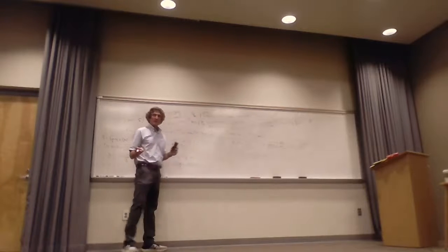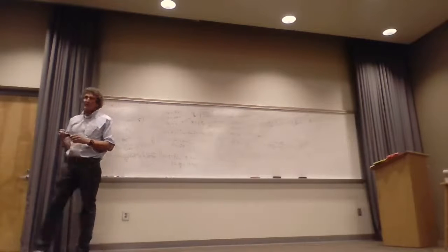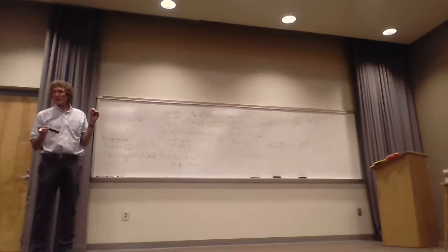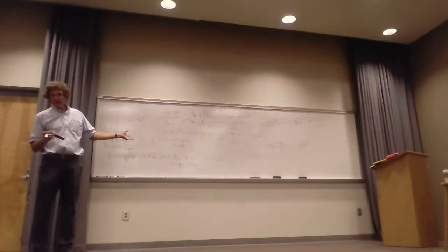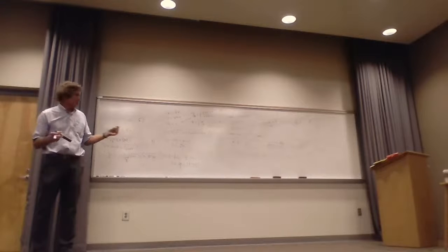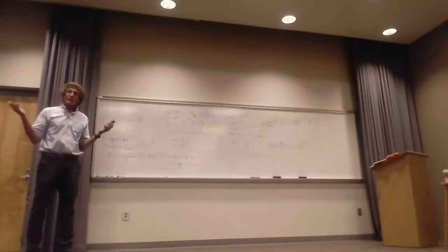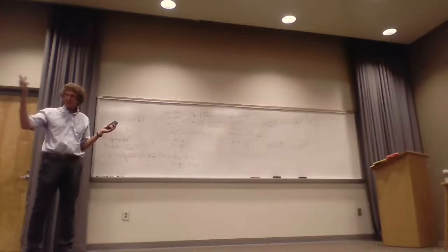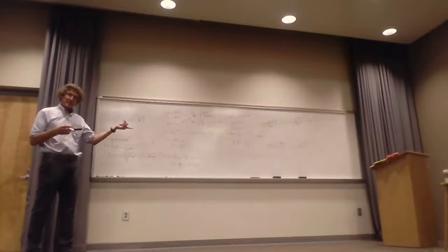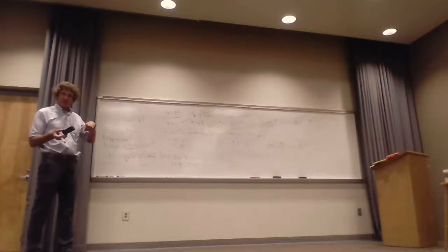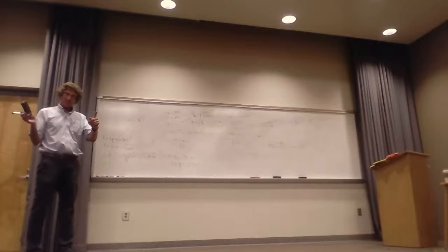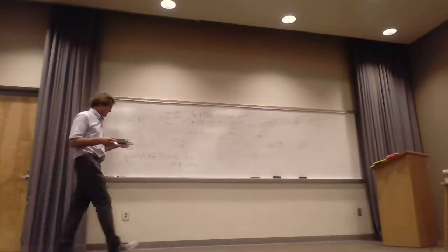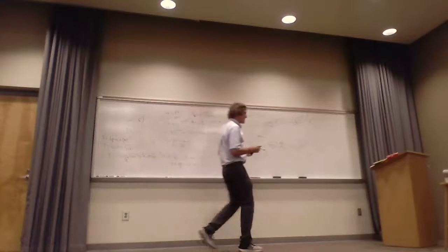All right, that's millimeter. When you get down to millimeter waves, you're at ultra small wavelengths. The reason is it's conducting. In free space at 10 to the 9th, the wavelength would be C over F. So you'd have 3 times 10 to the 8th over 10 to the 9th, or 30 centimeters, about a third of a meter. All right, that's sizable. This is trivial. What else do they want?